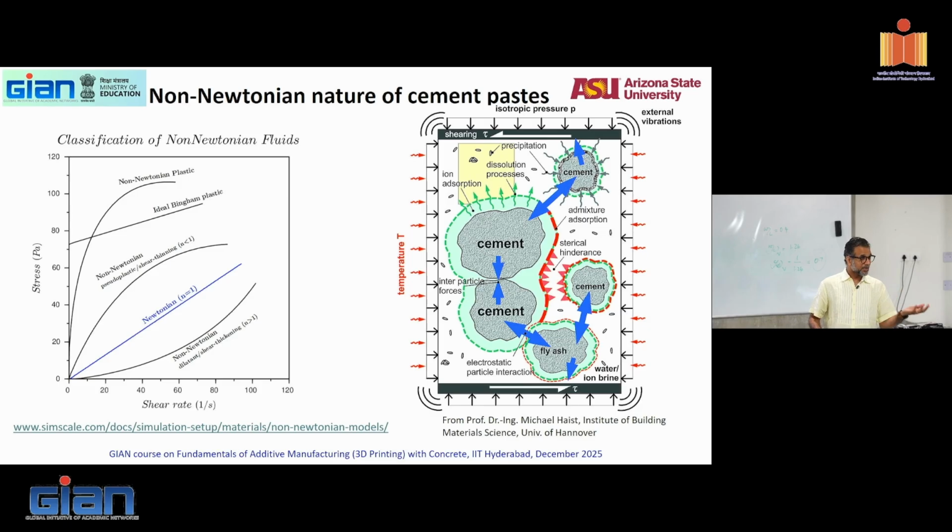Steric repulsion, hydration of cement. Cement is not going to sit in the system forever. As soon as it starts to connect with water, it's going to release ions. The solution is going to become concentrated with ions. Ionic solutions are going to start precipitating stuff depending on concentrations. That is going to change it. So lots of different reasons.